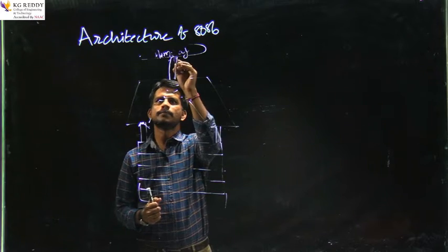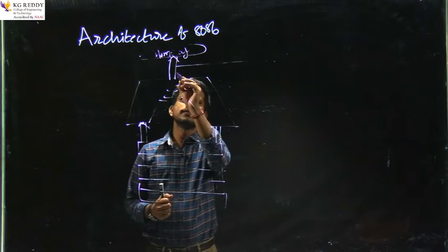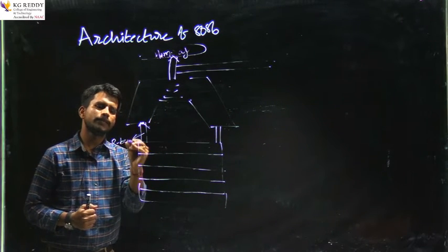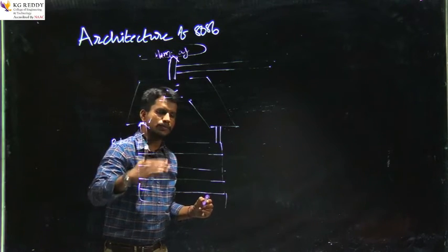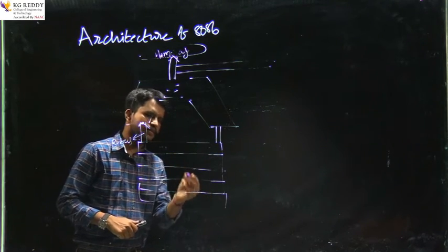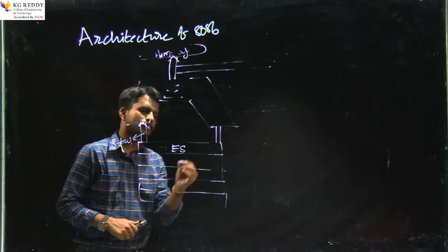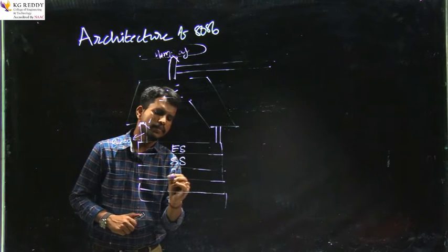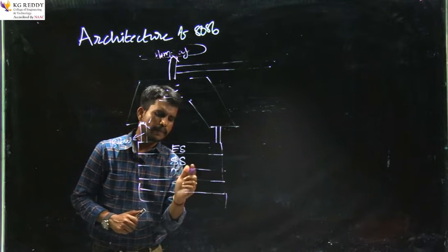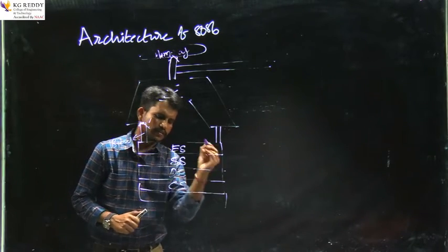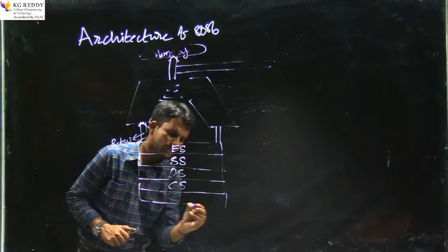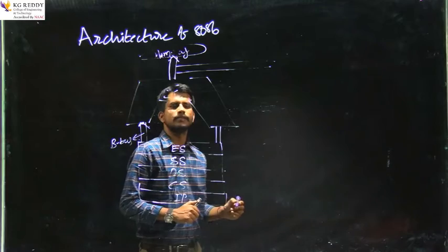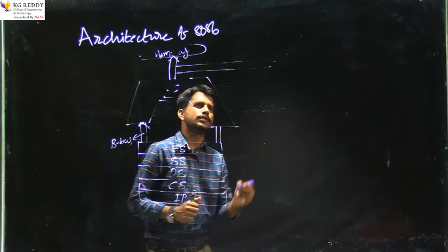Okay, right, and just observe the architecture, and this is a B bus where the data transfer takes place between the adder circuit and the segment registers, and these are the four different segment registers named extra segment represented with ES, next stack segment SS, data segment DS, and code segment CS. And finally, there will be one more 16-bit register location called instruction pointer, which will give us the instruction to be executed, right?